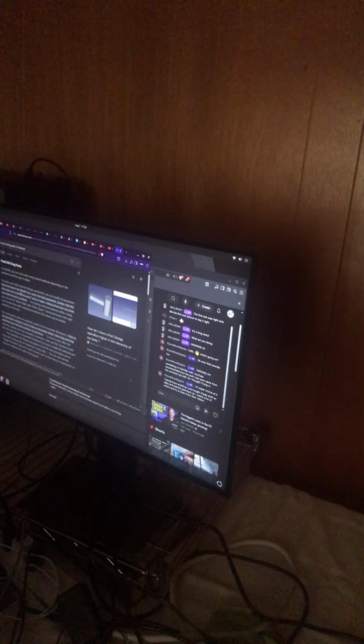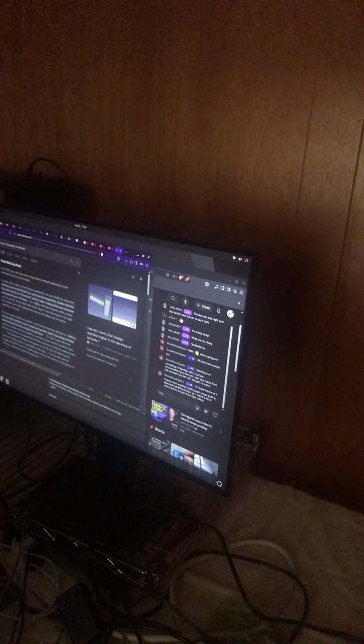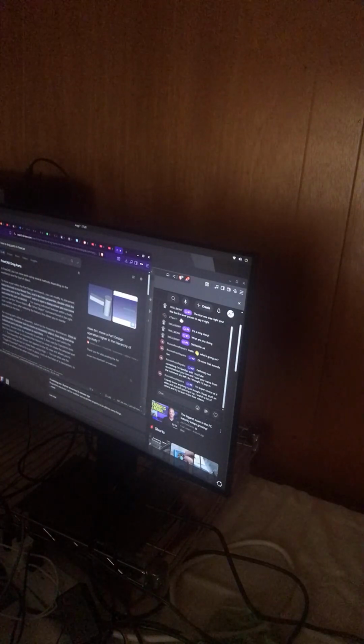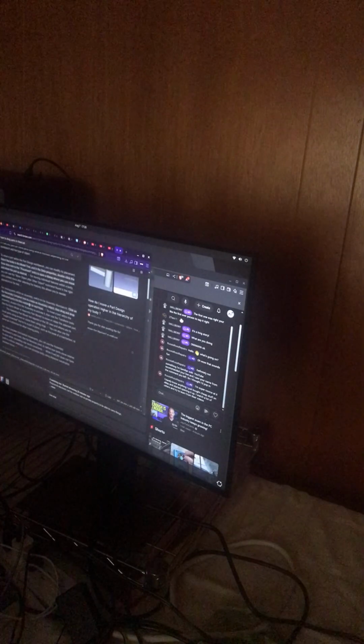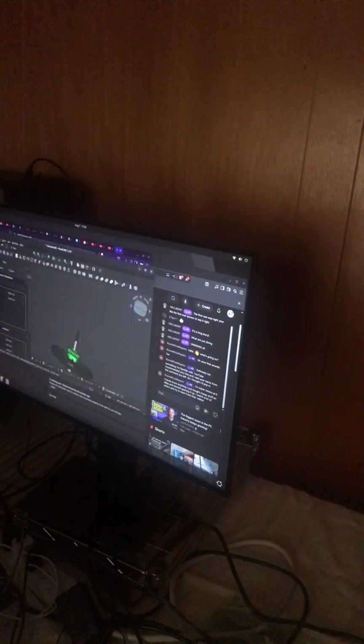Select the body in the model tree, and in the data properties, click the three dots in the placement entry, open a dialog where you can move and rotate the part as desired. For moving parts within an assembly, switch to the assembly workbench. Let's see what that is. Parts, assembly,